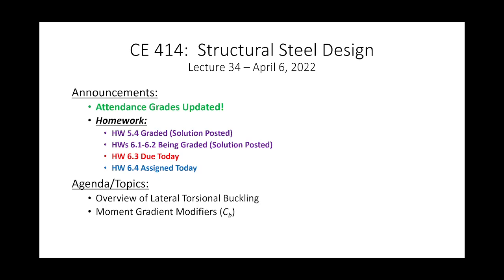All right, let's get started. Today, we begin our discussion of discretely braced beams, which I would argue is the more general case. I mean, continuously braced beams is a very specific case of beam design. It is the design where LB equals 0. But really, LB could be anything. So how do we handle that?